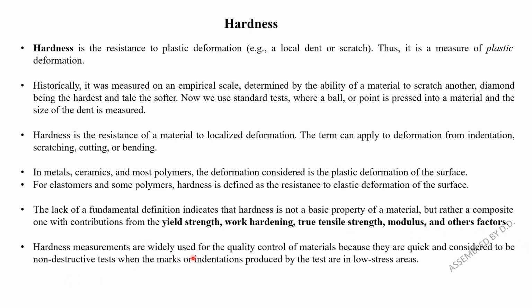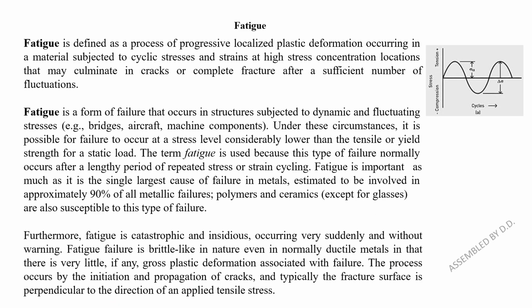Hardness measurements are widely used for the quality control of materials because they are quick and considered to be non-destructive tests when the marks or indentations produced by the test are in low stress areas. Let us see the last property, fatigue. Fatigue is defined as the process of progressive localized plastic deformation occurring in a material subjected to cyclic stresses and strains at high stress concentration locations that may culminate in cracks or complete fracture after a sufficient number of fluctuations.